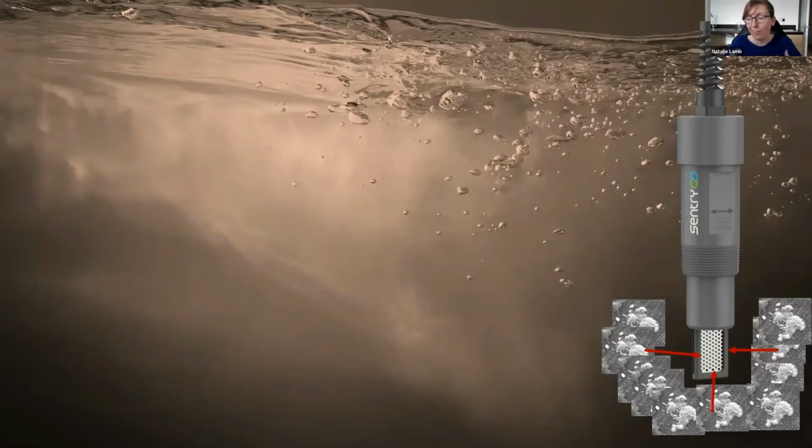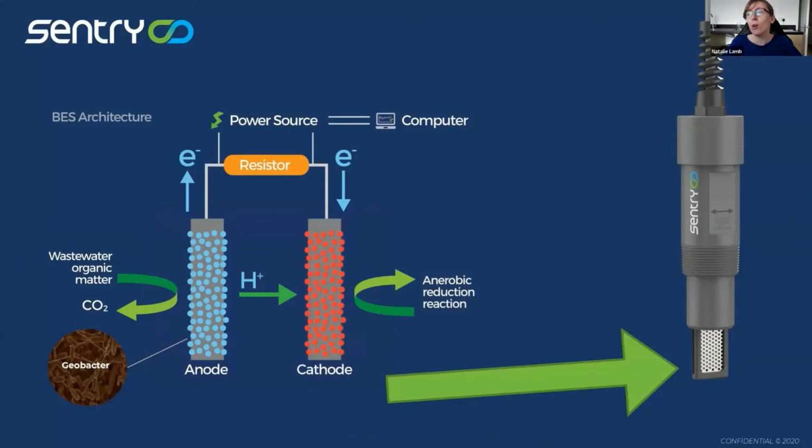So that's SENTRY and how it links into this biofilm and those microorganisms. What the SENTRY device actually does is, normally these microorganisms, when they respire, when they sort of breathe, give off electrons into the environment. But the SENTRY unit captures all of these electrons and counts them. In that way, it's able to count the number of microorganisms, the microbial abundance, wherever you're putting it in. So in that sewage process, in the treatment train, you're able to get a feel of the microbial abundance, and we're directly counting the respiration rate of the microorganisms that are there.